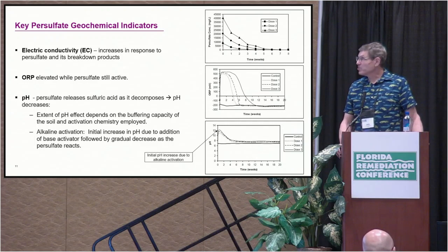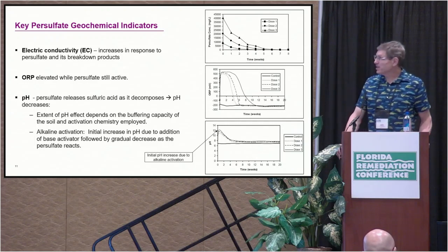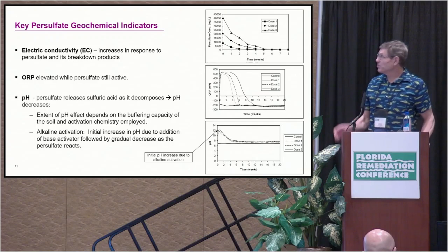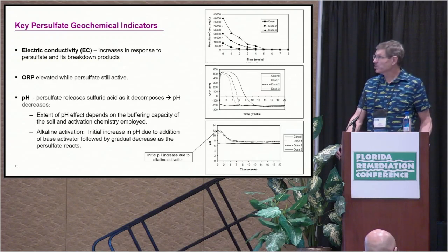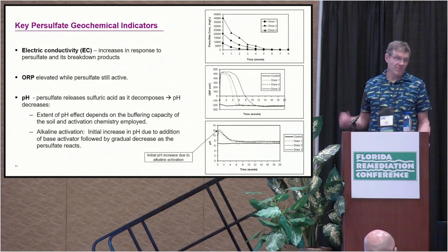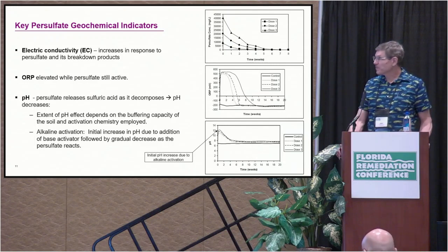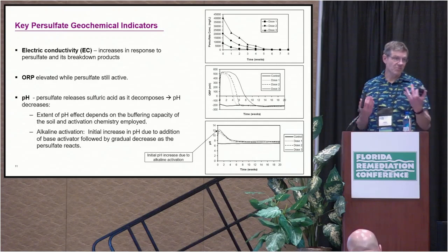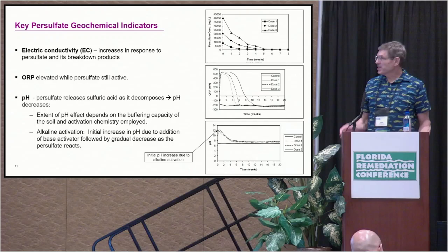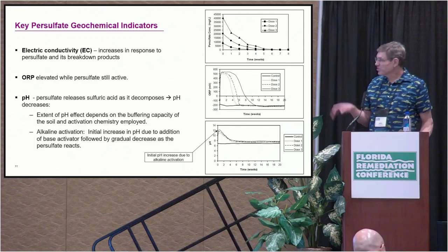Persulfate concentrations decline, and I had mentioned 2 to 8 weeks. You can see that sort of applies to what he was doing, because he was directly measuring persulfate in the lab. It declines fairly quickly. The ORP declines in the second graph as the persulfate does, because we're getting away from that strong ISCO environment. And then the pH, he was actually treating PAHs in equilibrium with sediment, so the pH is somewhat buffered by the soil, but you can also see that the pH in this case returns to a near neutral of around 8.